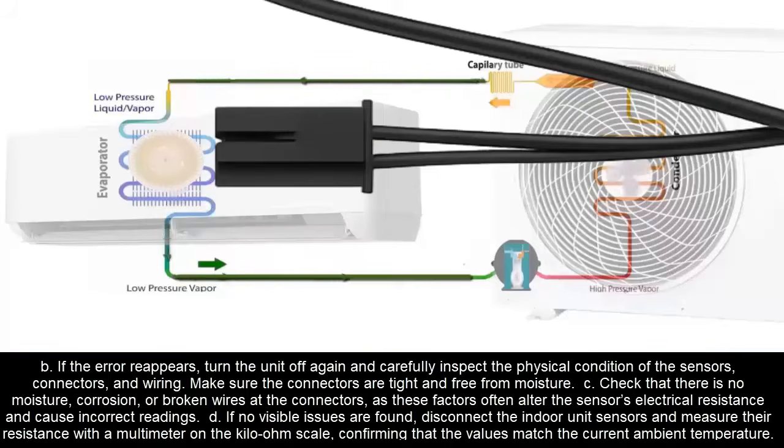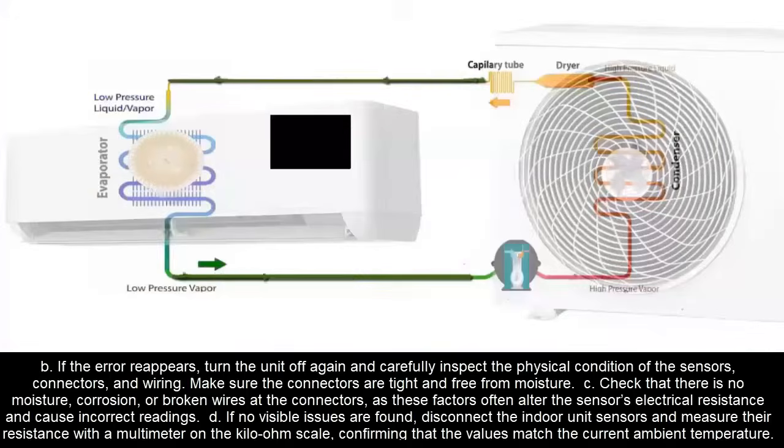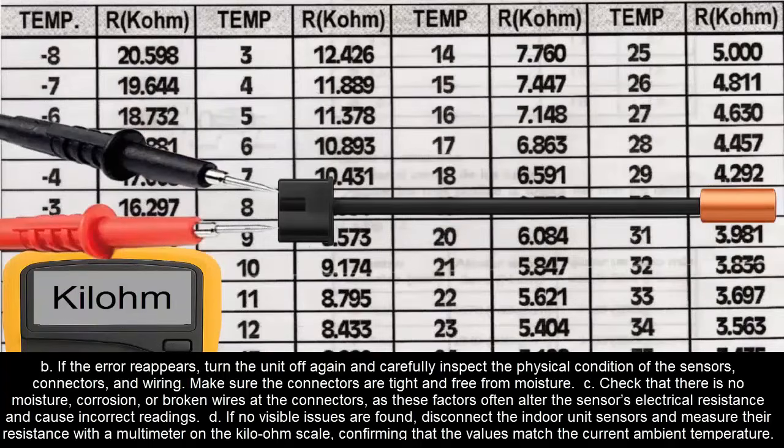C. Check that there is no moisture, corrosion, or broken wires at the connectors, as these factors often alter the sensor's resistance and cause incorrect readings. D. If no visible issues are found, disconnect the indoor unit sensors and measure their resistance with a multimeter on the kiloohm scale, confirming that the values match the current ambient temperature.